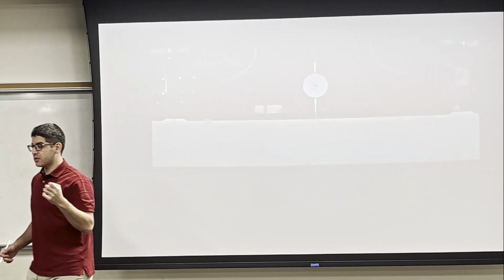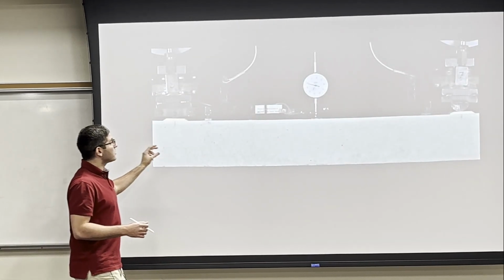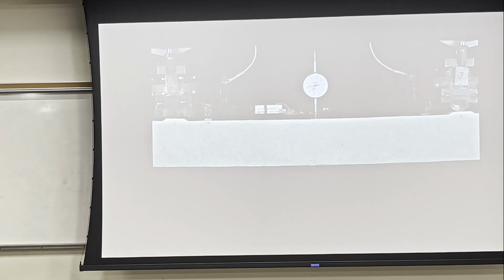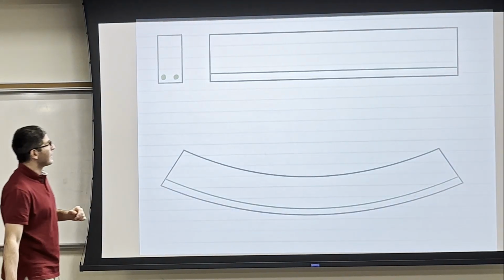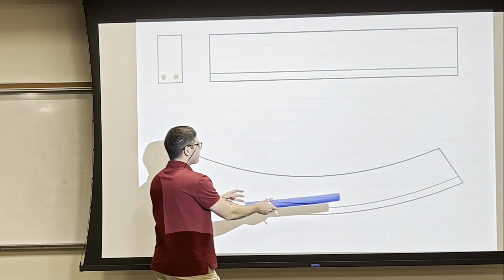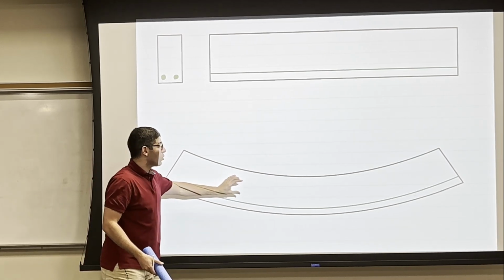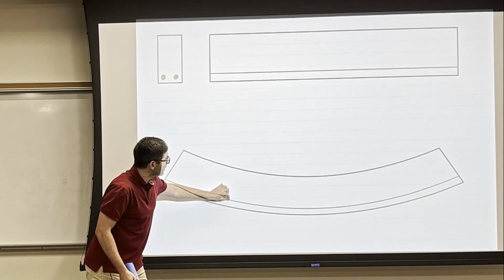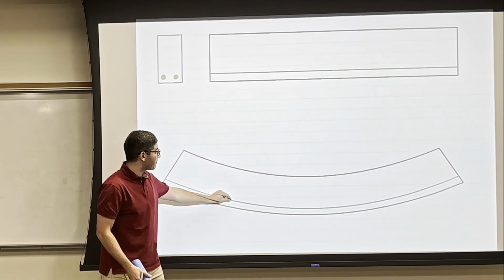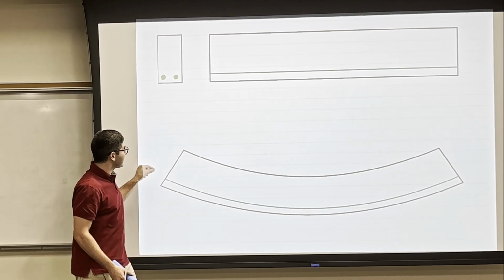So my point here is that the steel inside the beam, the rebar inside this cross section, was bending along with the beam, which tells you that at the interface between the reinforced concrete and the steel, they have the same strain. Because if they had different strain, you would see the steel pop out. If I want to draw the strain at any point here, I'm going to have tension at the bottom and compression at the top.